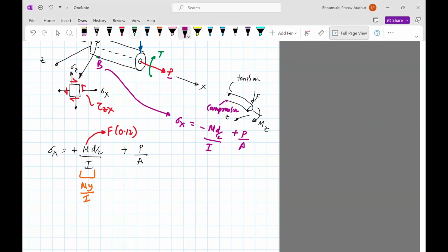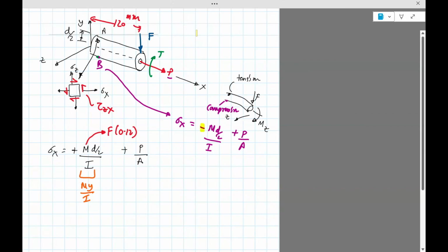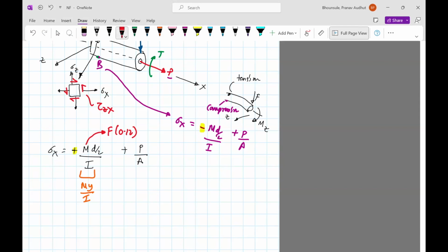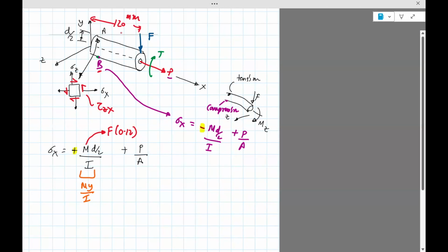So that is no doubt positive. So this is the difference, I guess. You see this is a negative sign, this is a positive sign. That stress is lower than the stress I compute at A. The stress at B is lower because of the negative sign, and it's higher at A. So just by playing with the points, you can get different stress.